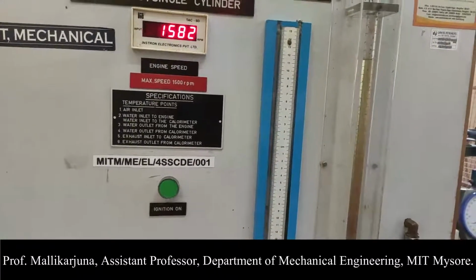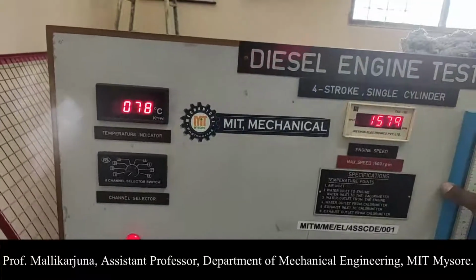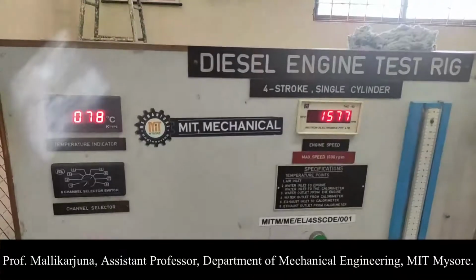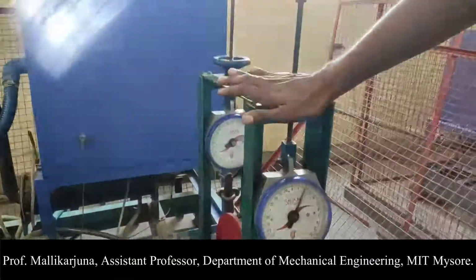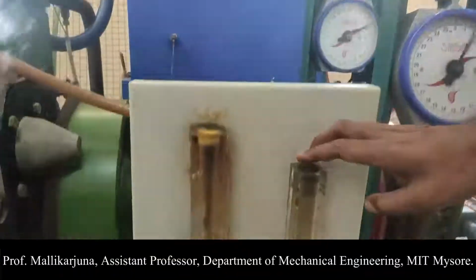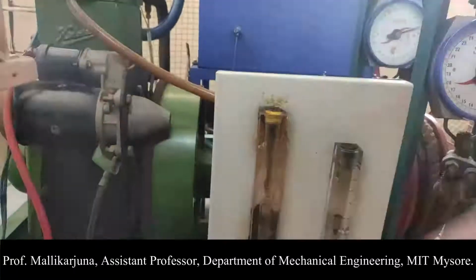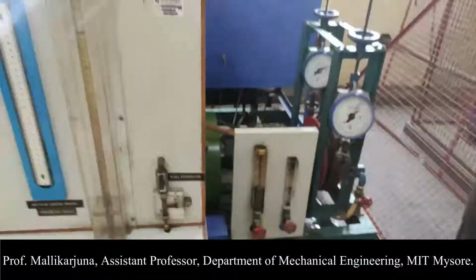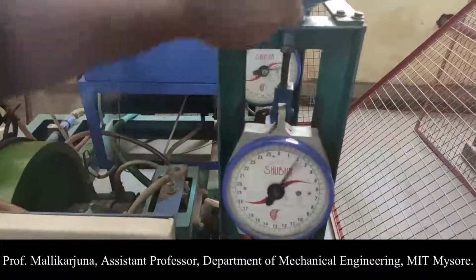So now in total the temperature, speed, pressure difference with which air is entering, and fuel supply, along with that the load on the engine and water supply to the engine as well as calorimeter need to be noted down for the trial. Let us start the second trial now by varying the load on the engine.